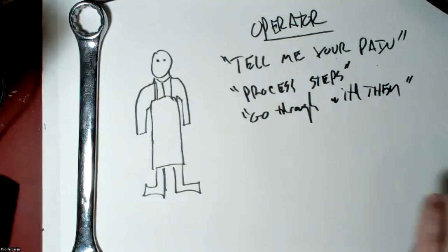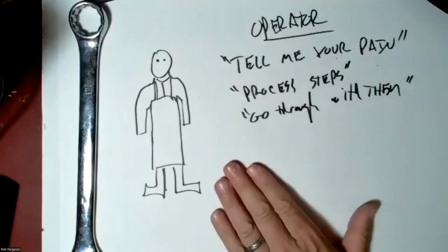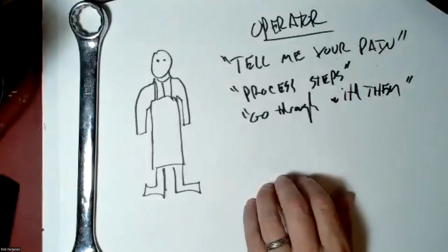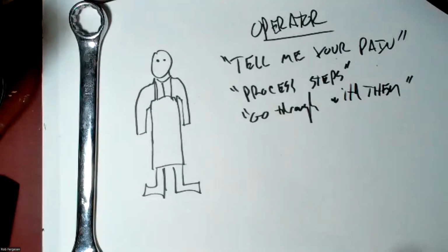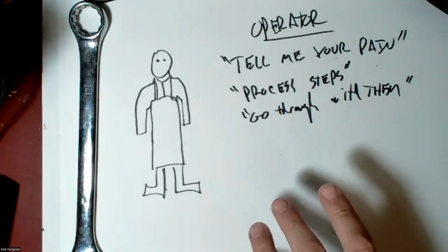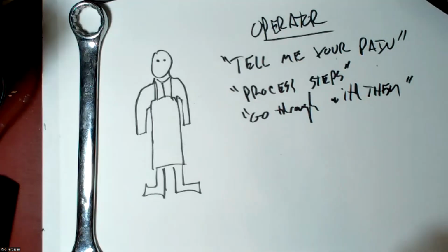And then you're going to document: open door, clean the part and the vise with air gun, pick up the finished part, place it on a tray, pick up a blank, place it in the vise, close the door, cycle the CNC machine, and the CNC machine will run, and then they'll open the door, and then they'll pick up the part and blow it off and start over the process again. All right?